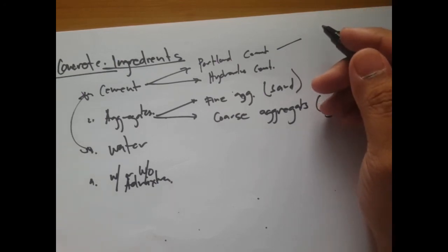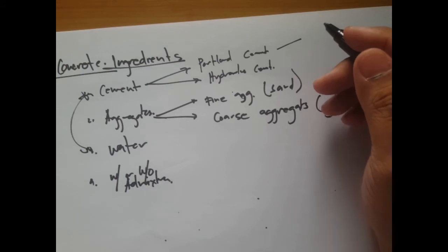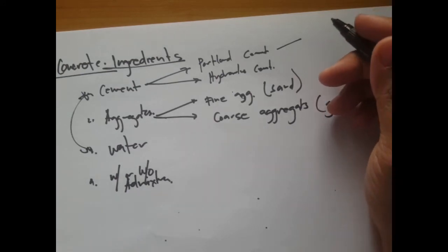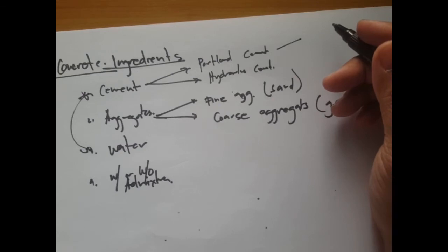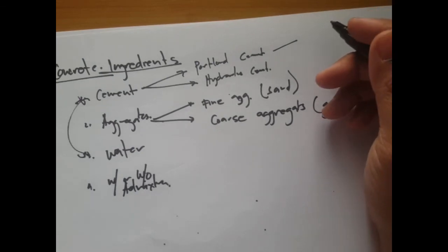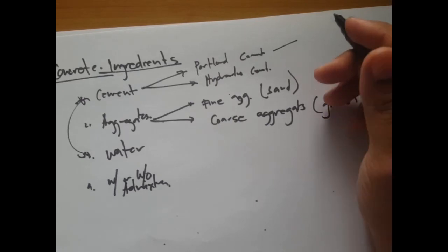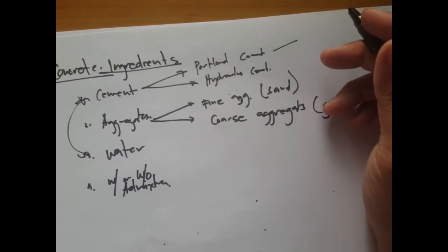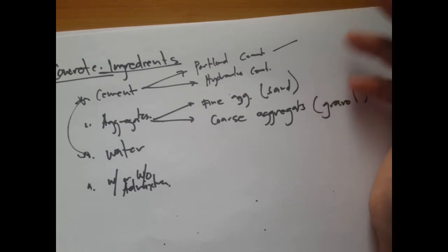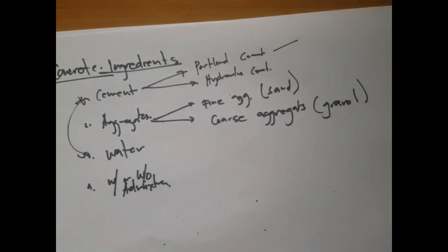For example, type 3 develops high early strength, approximately 190% of the strength compared to type 1. So with high early strength Portland cements, you can have early removal of the forms or shortening of setting time. Okay, and there are still many others.